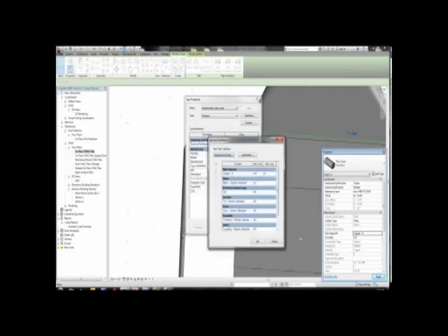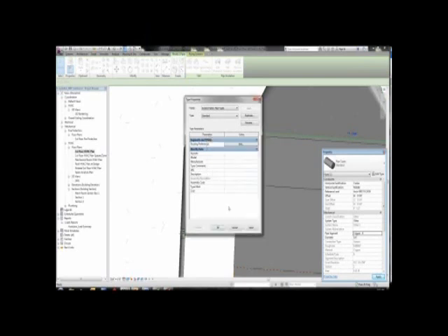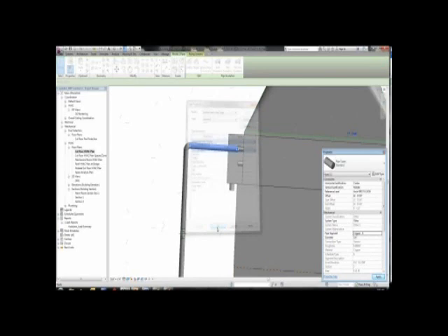So once I have the 5/8 in, I can now go back. And I can also choose in here, obviously I want to add that as the 5/8 inch size, or I could choose all or none, which would mean that the parts under none would never be used, and all means that the parts will always be used during the layout. So I could set this to 5/8, set this to all right now, and that's how the piping would behave.